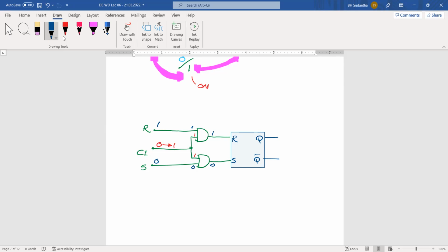Whatever the time that you change this 0 to 1, these outside R and S values will be transferred to the inside R and S inputs. It's originally 0, and to give these input values, we take it to 1, and after that we bring it back to 0. This is a kind of clock pulse. Because of that, we name this input as clock in.